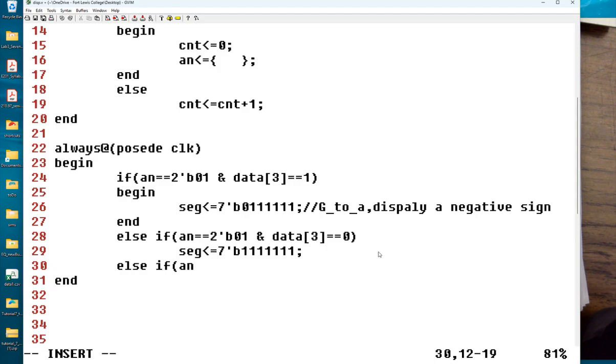But if you put else if, and there are other cases, they're not going to be covered, right? It's not going to synthesize, because it's not a real thing. It doesn't exist. It's a bug in the code. You can't hotwire that. If you're designing a toy, it's fine. If you're designing something for an airplane, probably not. For an airplane, you have to cover all the cases and make it super specific. It has to be else ifs, not else, right?